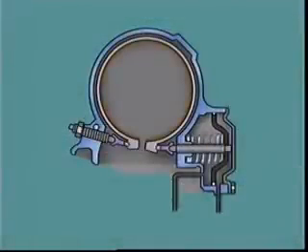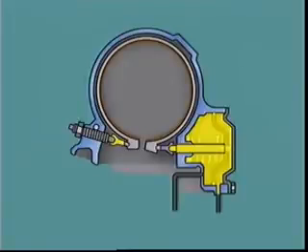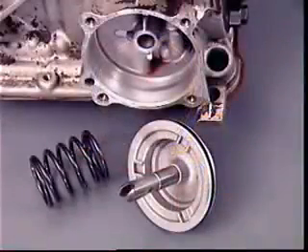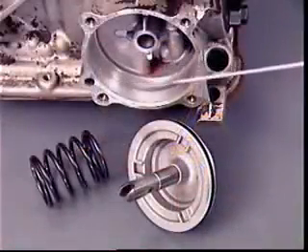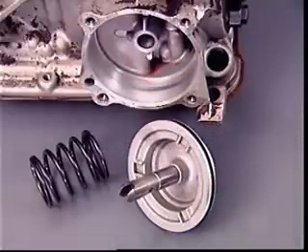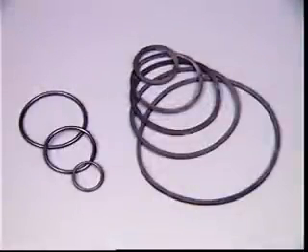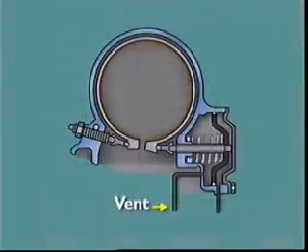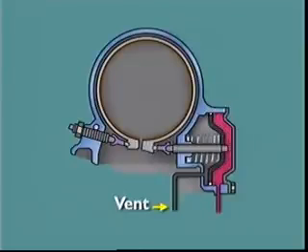One end of the band rests against a stop or strut in the transmission case. The other end accommodates a pushrod or linkage from a hydraulically operated servo, which contracts the band onto the drum. The simplest servo consists of a cylinder containing a piston, return spring, and a pushrod. Fluid leakage past the piston is normally prevented by neoprene-type seals. Fluid under pressure is directed onto the piston in the closed cylinder, moving it to apply the band.